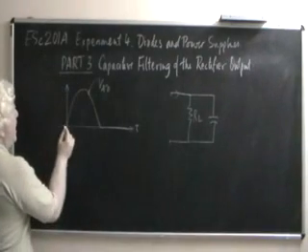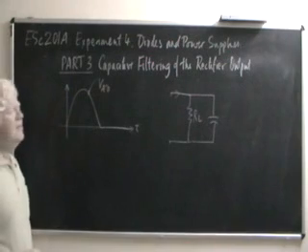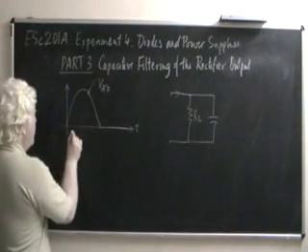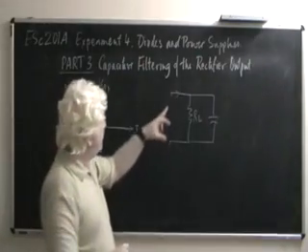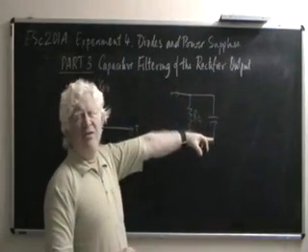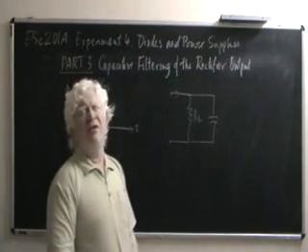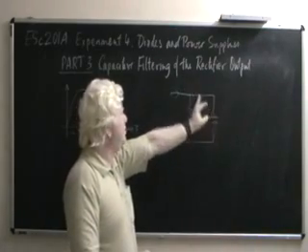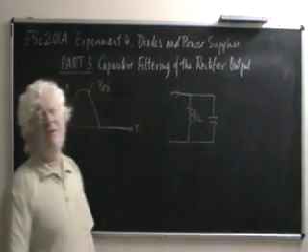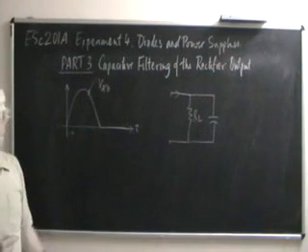Let us suppose that at this point of time the capacitor voltage was 0. Then, as time proceeds beyond this point, there is a positive voltage being applied, the capacitor is uncharged, and with a very, very small time constant, because there is literally no resistance in series with the capacitor, the capacitor voltage will follow the supply voltage.